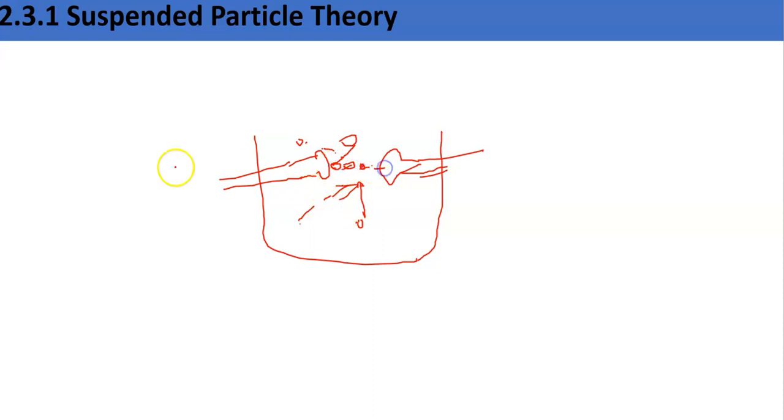A chain is formed. Now you tell me, we are observing a liquid dielectric material where the dielectric strength, the breakdown strength of the liquid, is very large. Here you are considering that a chain of suspended particles has formed, which are solid materials like paper, fiber, cellulose, tissues. The dielectric strength of that solid is very weak compared to the oil. So you are forcing the weak material inside, with weak suspended particles in between very high stresses.